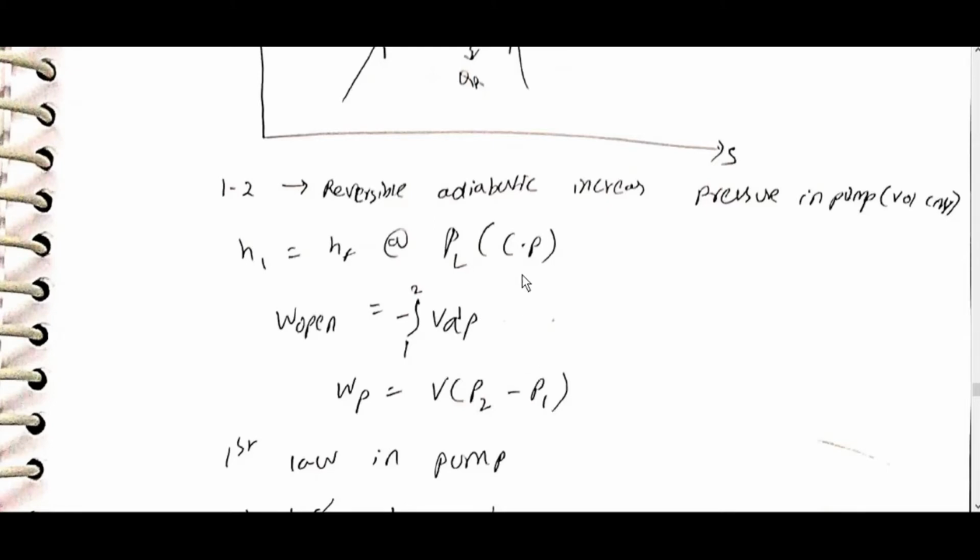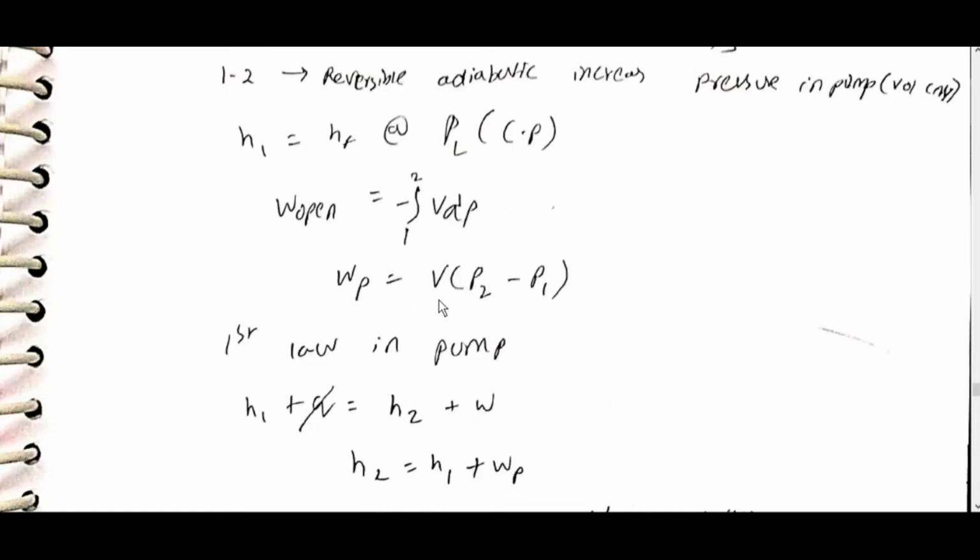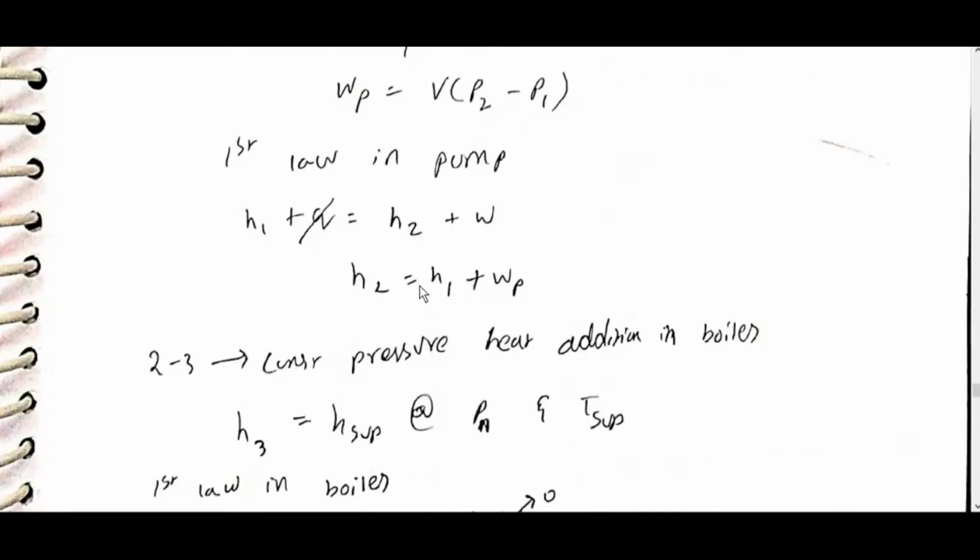W open is equal to minus integral 1 to 2 VdP. W pump is equal to V into P2 minus P1. First law in pump: H1 plus Q is equal to H2 plus W.